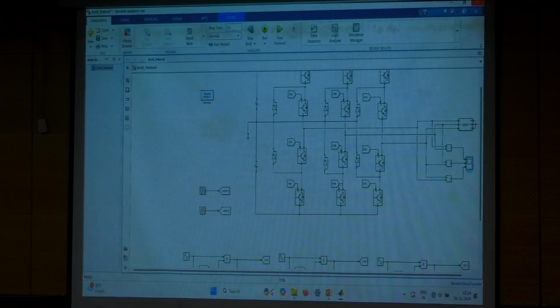The biggest difficulty in the hardware, especially if you are using platforms like dSPACE or FPGA, is the sampling time, right? All your simulation is supposed to be done within that period, otherwise it will throw an overrun exception within that time, right? We have to make sure that, at least for real time operation, everything is finished within 50 microsecond. That is the best thing, right?